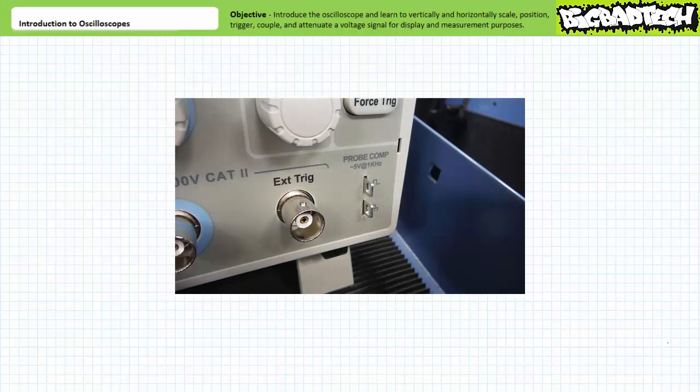Ordinarily, a function generator could be used to create such a waveform. However, the Tektronix TBS 1032B conveniently features a test point on the lower right-hand side that continuously generates this exact waveform. This test point can be used for initial setup of the oscope and demonstration of basic oscope scaling functions. Before we view this test waveform in the oscope, let's briefly examine an oscope probe.